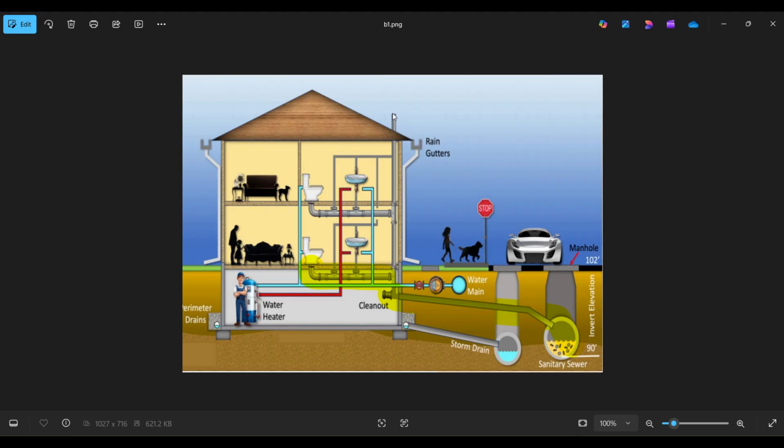Similar thing happens with our rainwater, so for our storm water, but for our sanitary water we have three pipes that need to intermix with each other. They are not three structurally different pipes, but they have different uses. We have a drain water, we have a sanitary water, and then we have a vent. So the material of these particular pipes is the same, but the uses are different. I'm going to be explaining this in the upcoming parts of this particular masterclass.